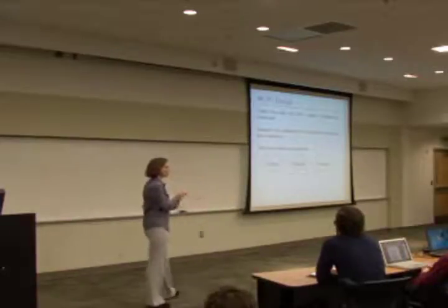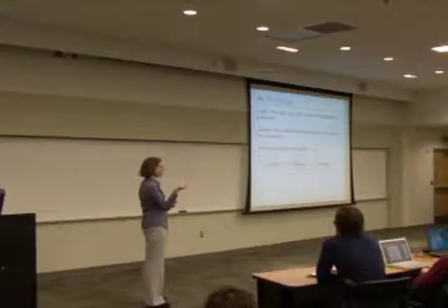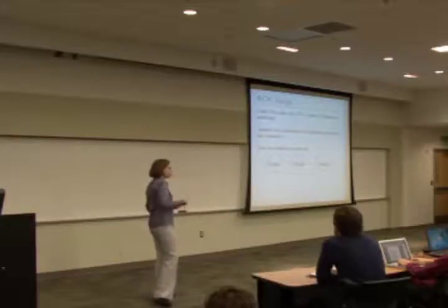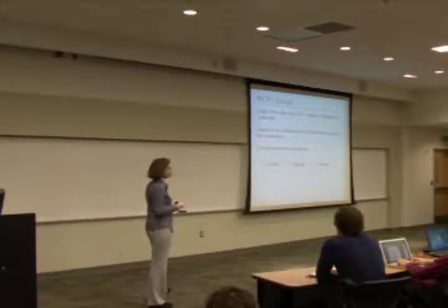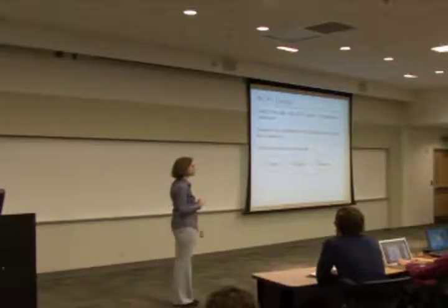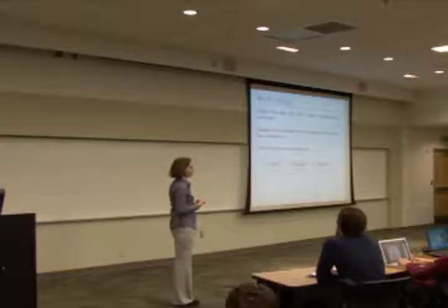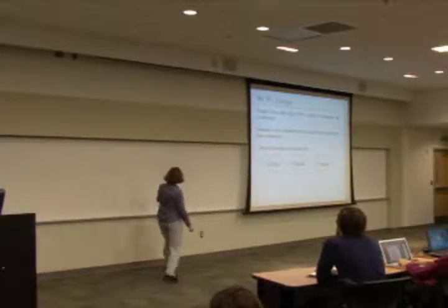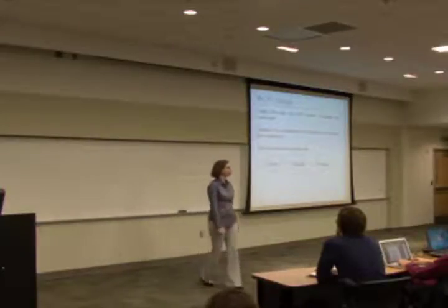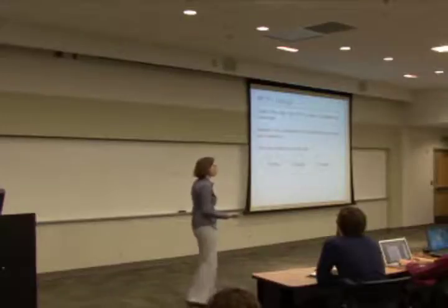So the first step is that PC writes into address in a memory, and then the second step would be to write from a memory instruction into instruction register, and we'll see that we need a third step, which is, guess what? We have to move from instruction 1 to instruction 2, which means we need to increase the PC. Program counter has to be increased.